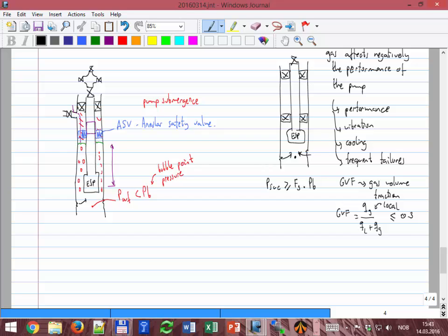They say, all the time, let's say this factor you can put 1.1, you can put 10%, 5%. The bubble point pressure in the case of Peregrino, I think, is 30 bar. So I want my suction pressure all the time, no matter what, to be single-phase liquid coming into the pump. And like that, I just solve the problem: no gas, no problems with gas, no problems with producing through the annulus, accumulation.